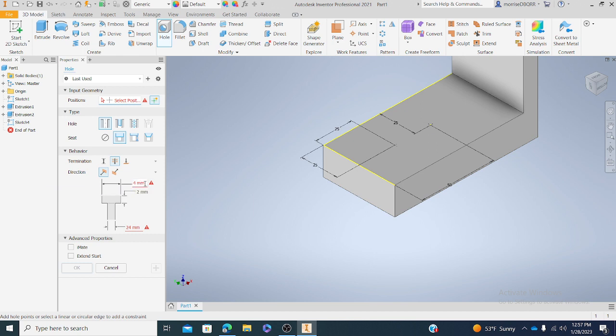All right. Now, when you click on this, let me give you the dimensions here. This outer diameter that you see here should be 17.2. All right. And this dimension here needs to be 10.8. All right. And then this dimension right here is the depth. This needs to be 11.5. And I'm going to click on those two points that we put earlier there.